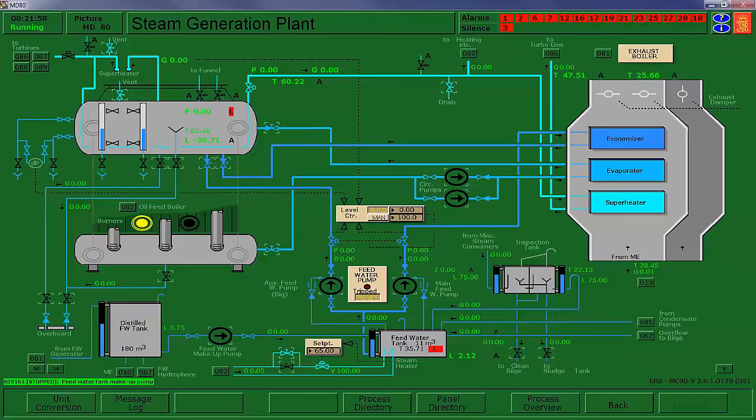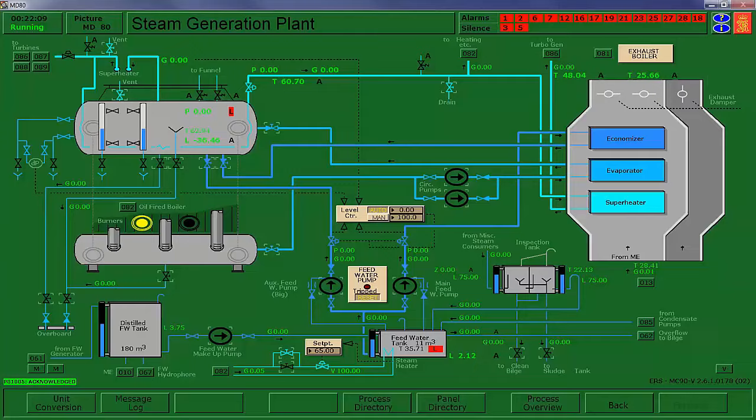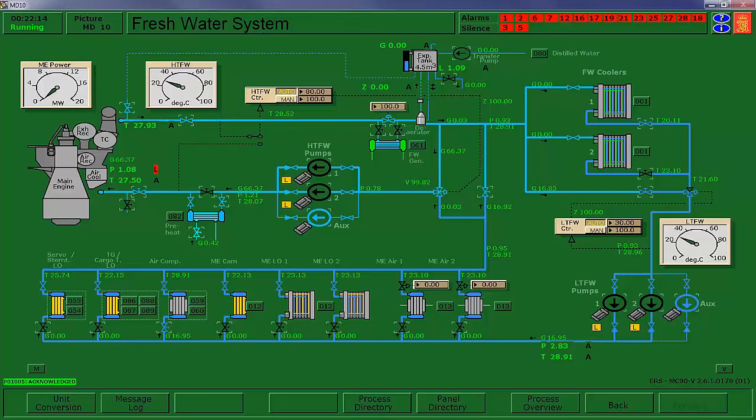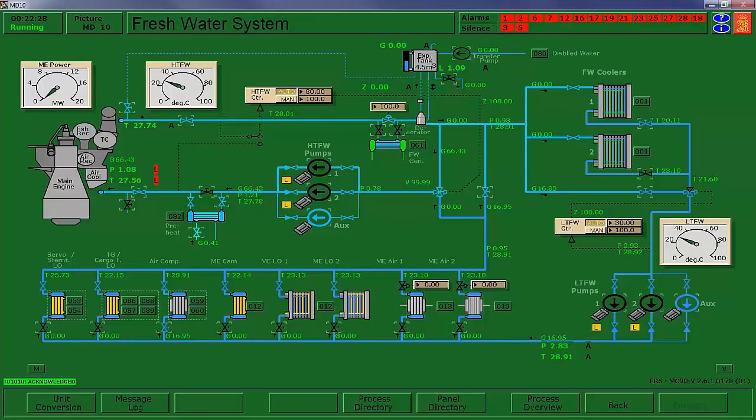Normally they'll shut it off a little earlier, typically after you pump down the condenser. Okay. Low temperature on the high temp, and of course that is going to be true, right? You'll also get a low pressure and a low temp. We're only running the auxiliary pump. Think about it, this is the same as the keep warms on the Bear, a much smaller pump just to circulate water.